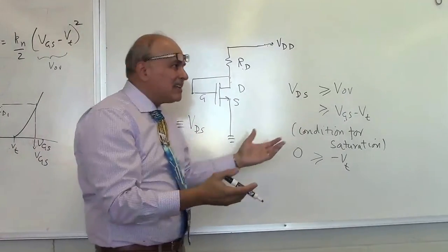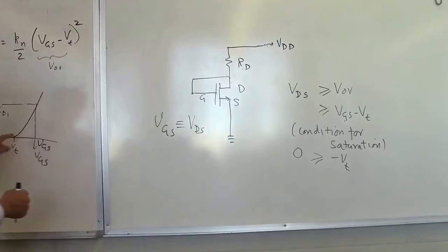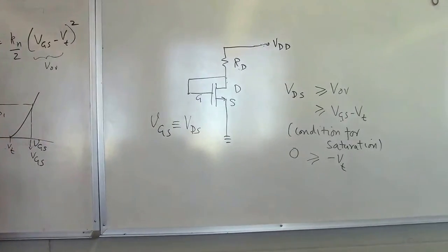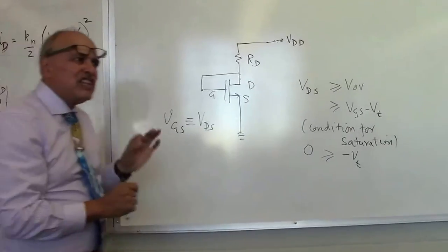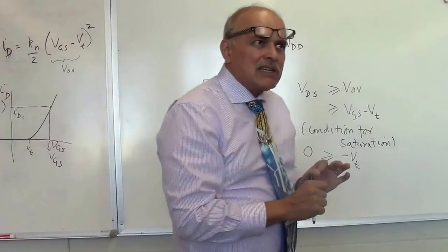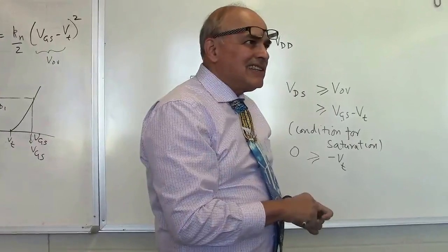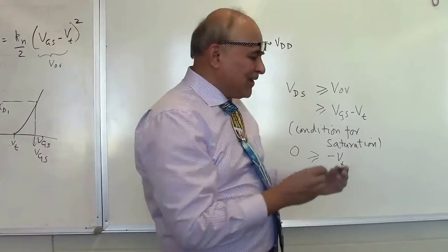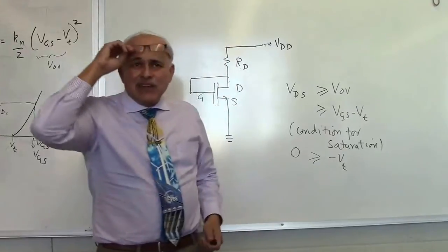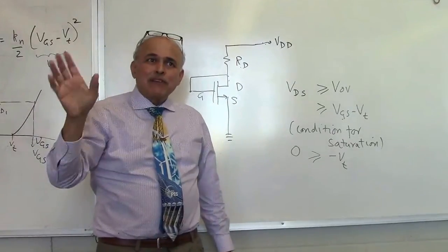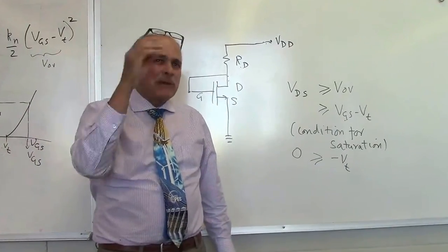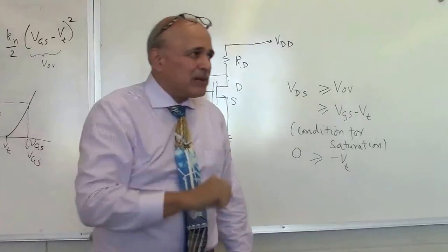So you can then get this characteristic. You should be able to repeat this characteristic and get exactly what's on your data sheet to the millionth decimal place. Does that ever happen in any lab? Okay. So hopefully you're good to be good within 10%. Because again, you might be quite off, because every MOSFET is different. Those are only typical characteristics they give you. It actually varies quite a bit.